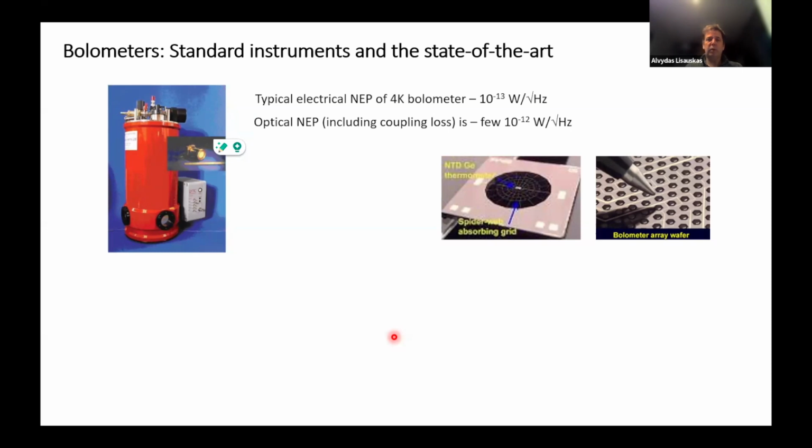And the principle of the bolometer is applied in very different applications. For example, here are photos of one, where the thermal element or absorber is placed directly in the center, with a spider web to limit the thermal capacity and the thermal link to the thermal bath.